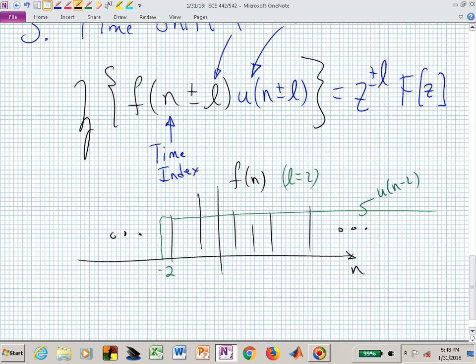We just want to Z transform everything that's on or underneath or windowed by this unit step that's delayed by the same amount. And I'll just say there's f of n. And we'll figure out how much you needed to delay it depending on your particular problem. That's the easy one, and this is the time shift property you would use if you were trying to find a transfer function, because we don't worry about initial conditions when we're trying to find a transfer function. We just worry about the amount of advance or delay, and we scale that transform by the appropriate advance or delay.